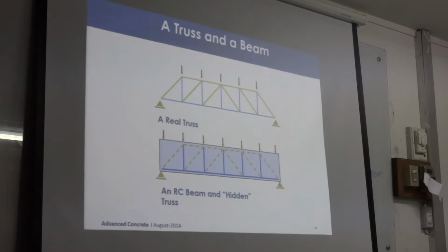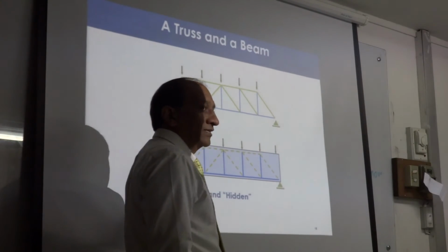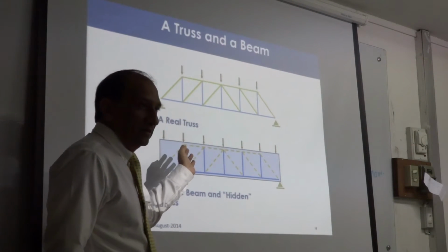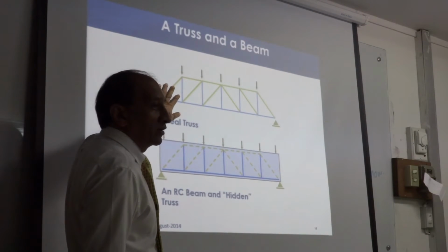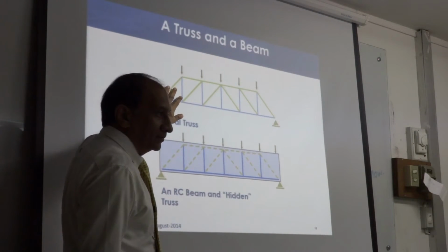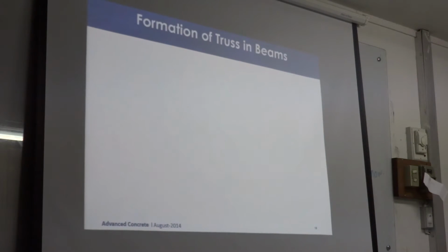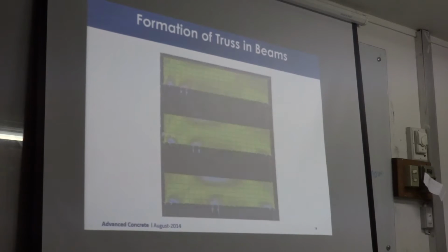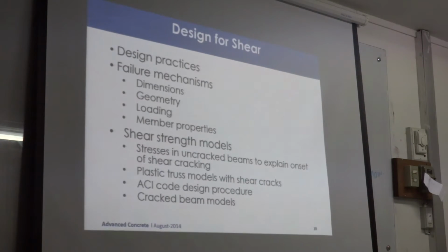And if it's an inclined beam or a staircase or something like that, it will have all 6 of them. So the problem then comes that if we have all 6 of the actions coming at the same time, how do we design and put the reinforcement together? And how do we do this all in one go? One of the ways to handle them all together is the space stress analogy, right? Which I'm not going to discuss now because that is the next topic.